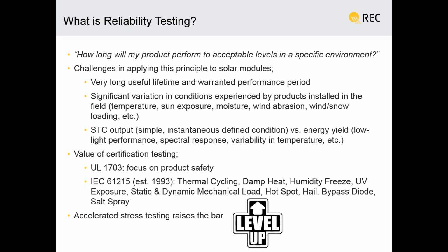Standard test condition output is one specific set of conditions. Ultra important to realize in this industry is that the number that we're so calibrated to look at, that's one specific temperature, one specific air mass, one specific speed, one specific irradiance, which is fairly high, 1,000 watts per square meter. And in real life, you get a whole bunch of other things that creep in that impact the ability of this product to produce kilowatt hours of energy.